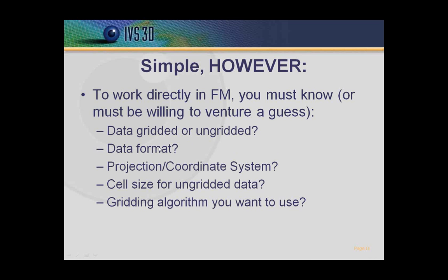You want to know your data format. This isn't as important. With ungridded data, we often know what the data format is based on the library and the file extension. Sometimes with gridded files, when you import them, you're going to have to choose the type of file it is. Again, if you don't know for sure, make a guess, and if it doesn't work, you can try again. You're going to need to know the projection and coordinate system information. You would find that in the metadata for the files, perhaps in a survey report, but it is important, and you will need to know this information.